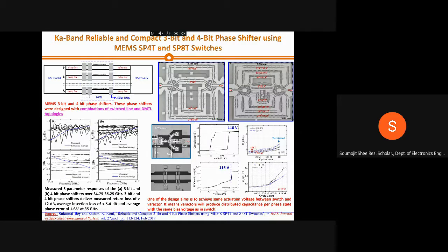Yeah. So the gap width is more. Also, keeping the line width the same, if you are increasing the gap, then you are increasing the impedance of your coplanar waveguide, so the CPW impedance will be more. Now if you add the capacitor, then again the overall, collective impedance will be reduced. So that is the overall story.